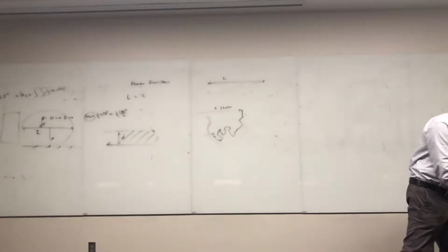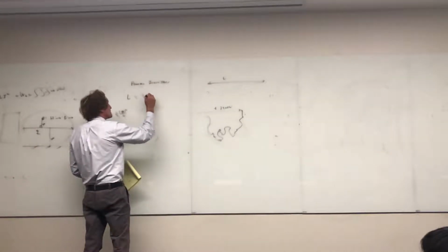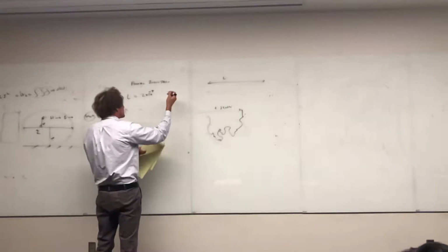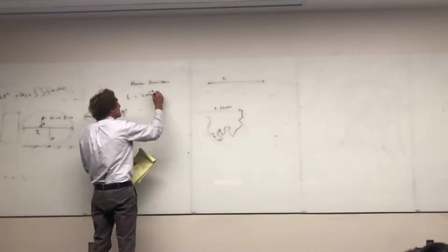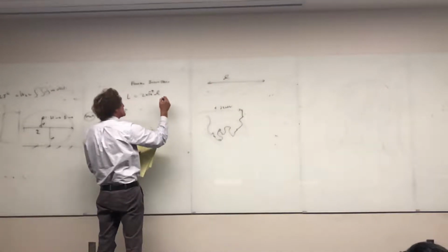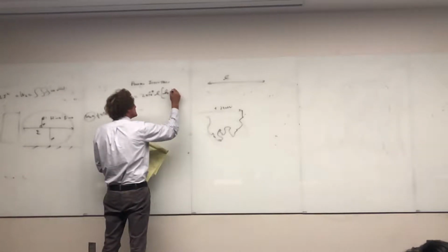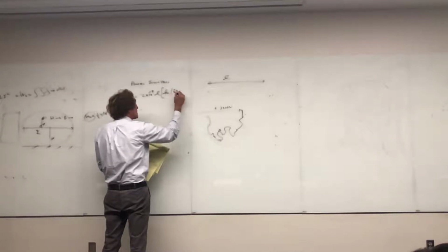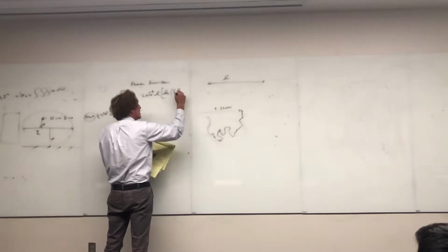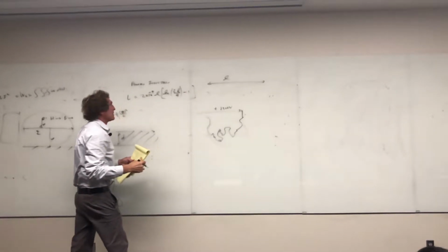2 times 10 to the minus 7th. Other books have a different constant for this, and they adapt a different constant in the equation, times the actual length of the wire. And I better use a small l here, or we'll get confused. That's the length of the wire. This is all in meters. And then it's going to be times the natural log of 2 times the length of the wire over the radius of the wire, minus 1. And that will be in henries.